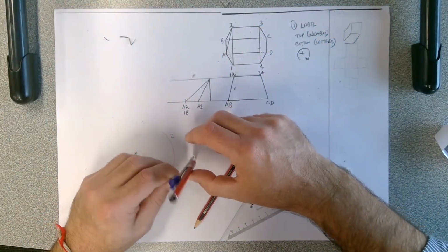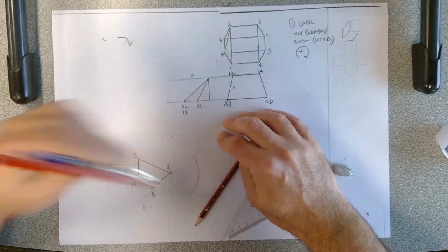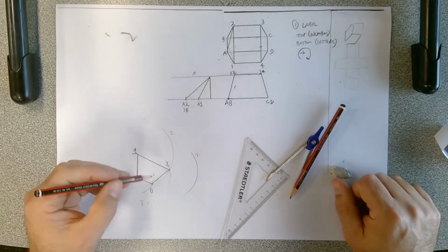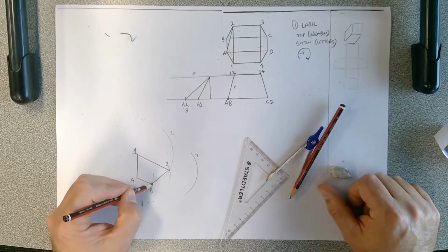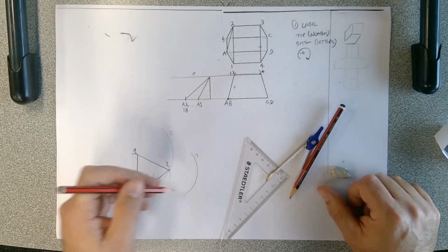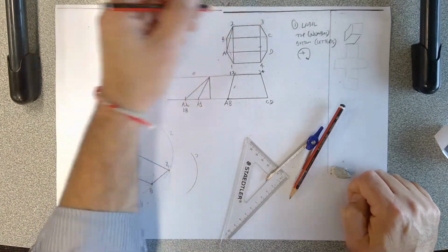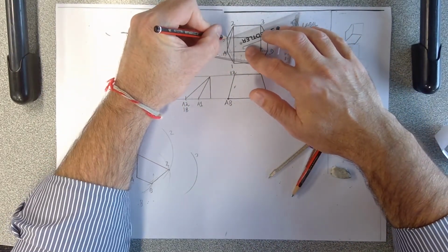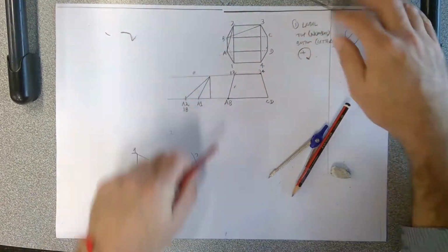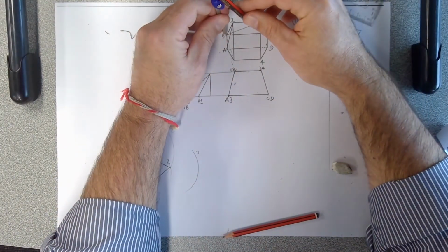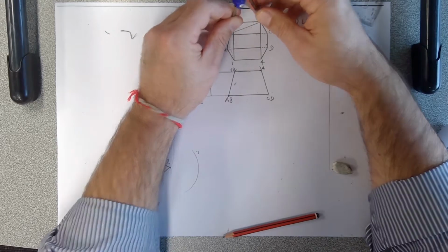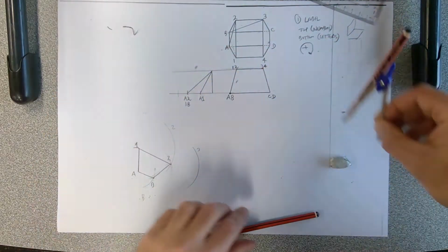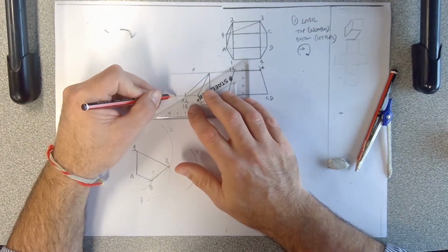We're going to swing our arc nice and wide, 2 to 3. That's our 2 to 3 arc. We need to find another line that goes to 3. We know B, so we're going to take our line B3. So we've got B and 3. Now we need to, you guessed it, create a triangle in that face. Triangulation of the faces. B3. Then we grab our compass, put it on B3. Boom. Then we come over here to this graph, draw the swing and arc, and this is the true length of B3.